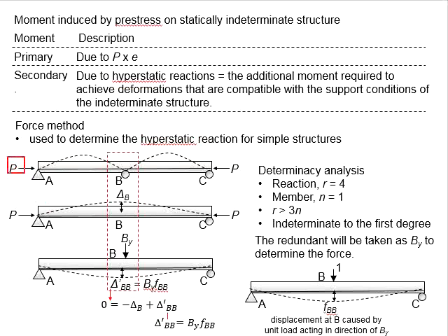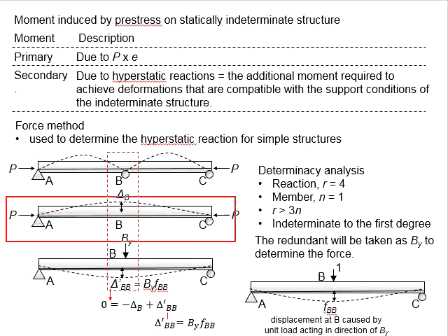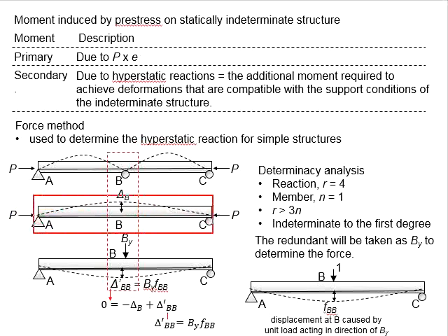Having this prestressing force times the eccentricity, it will generate a moment acting on the member, which, if without the reaction at the middle, the member should theoretically perform in this manner, same as the response of a simply supported member of the equivalent length.